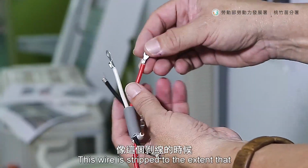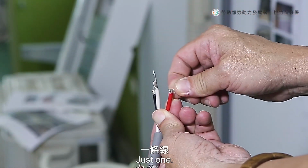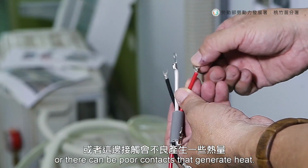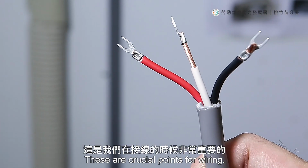This wire is stripped to the extent that only one thread is left. Just one. With just one thread, when the large current flows through it, it can melt. Or there can be poor contacts that generate heat. These are crucial points for wiring.